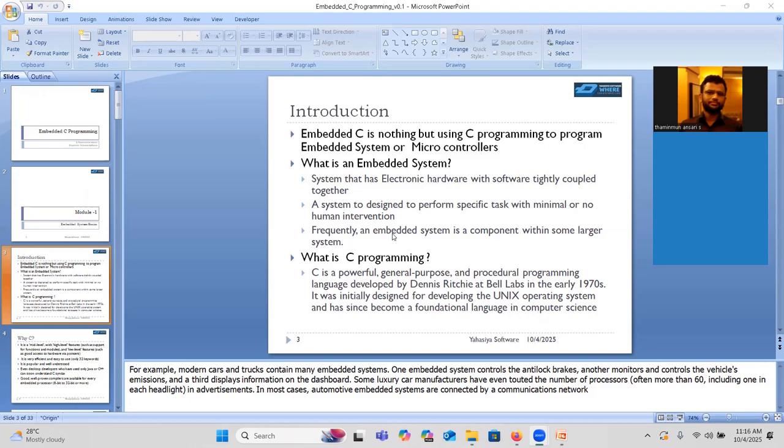Yes, sir. From my understanding, they may be using servo motors, which can create a specific angle whenever the speed information is received. Yeah, it is not servo, it is a stepper motor. There is a stepper motor which can make the deflections. A small stepper motor is used for every gauge. These motors are interfaced with the microcontroller using a peripheral interface, or IO interface.